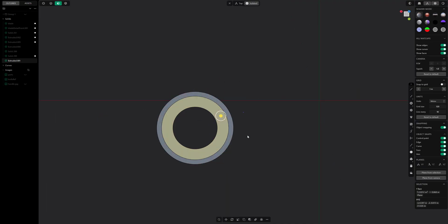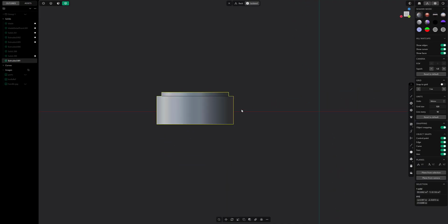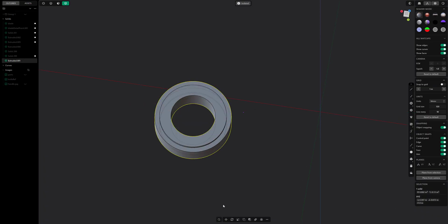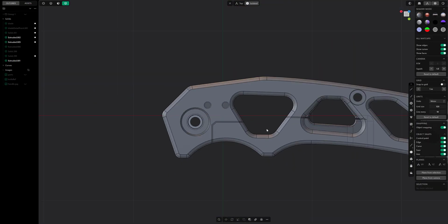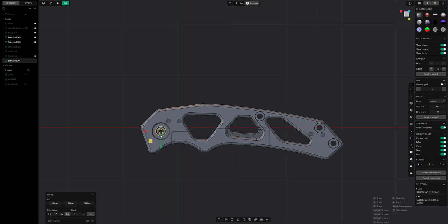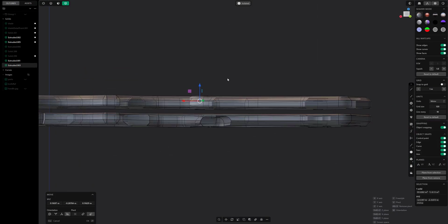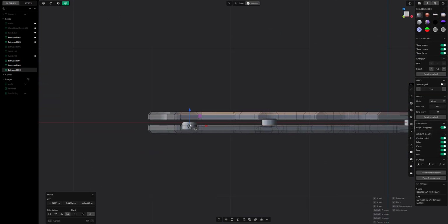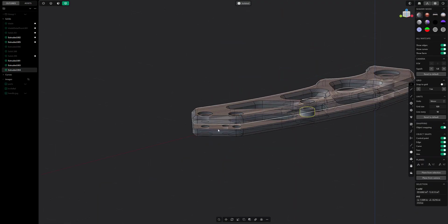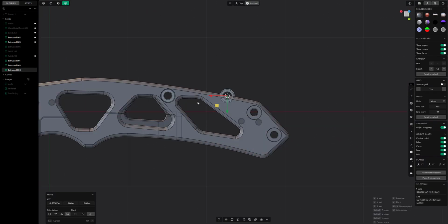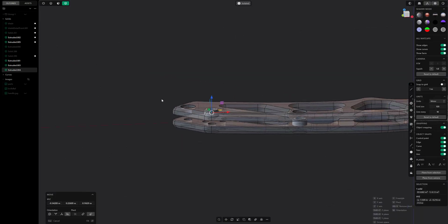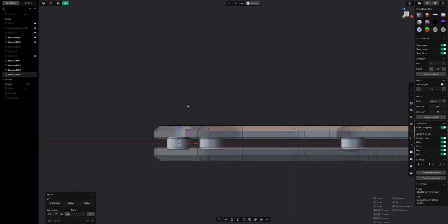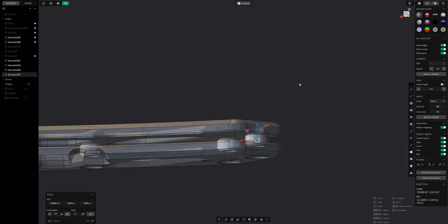So yeah, it's more like this. You can see it's just a spacer that goes between, and then just mirror it. Try it again. Mirror. Make sure you click combine, then you don't have to boolean them together. So here's the spacer that exists at each one of the locations of hardware. I'm just going to duplicate those and put them in place. It's pretty simple. Just move it down, duplicate the last one, move it into place.